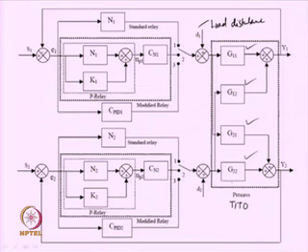So, in spite of having load disturbances, I do not mind, because I have got a PI controller while conducting the relay test, the effects of load disturbances can be nullified or can be minimized, okay, or can be eliminated with the help of the PI controller. Therefore, the use of modified relay results in multiple benefits. It can avoid the ill effects of load disturbances also while performing the relay test.